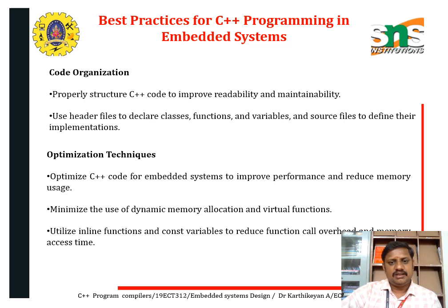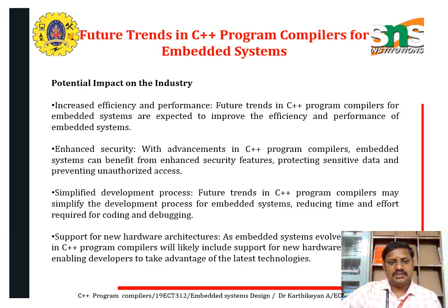The code organization and optimization techniques we are also using: minimize the usage of dynamic memory allocation and virtual functions in C++ for embedded systems, and utilize inline functions and constant variables to reduce the function call overhead and the access time. So in potential industrial applications, we are reducing the impact.